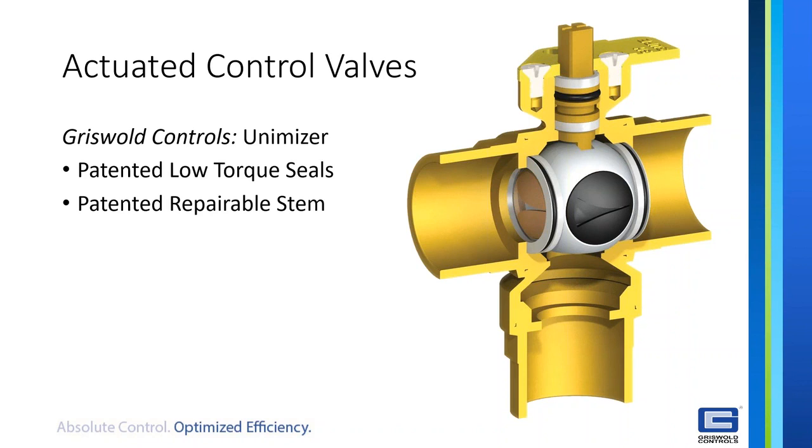And so what that means is a traditional ball valve requires a 30 to 35 inch-pound actuator to rotate a 1/2 and 3/4 inch valve. That's very normal, that's kind of what's normal on the market. Ours actually only requires about 20. So we could do smaller actuators, but most of the actuators in the industry start at about 30, 35.